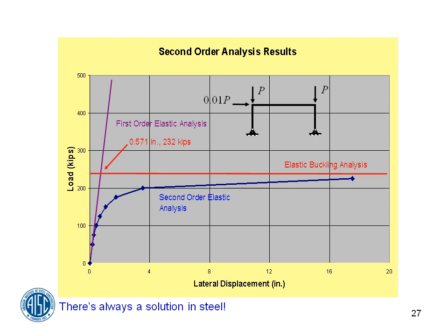The structure buckles. We need to know that level. We'll talk about that later. But certainly the typical first-order analysis that moves up this line can't reflect the true behavior in the structure. So we need to accommodate a way to calculate the second-order effects.